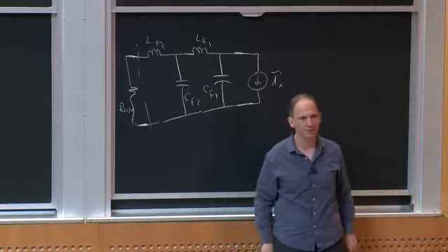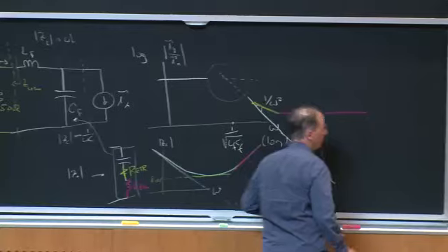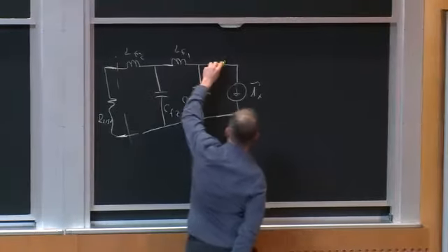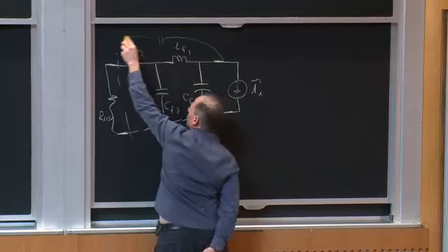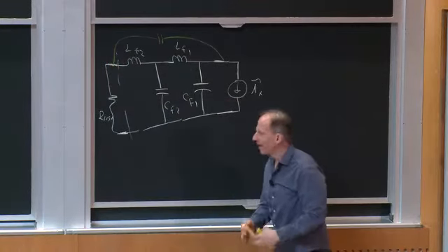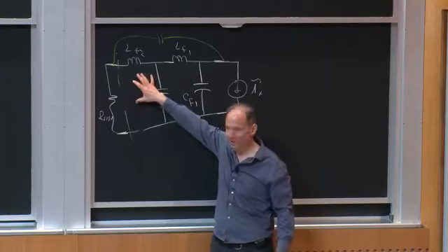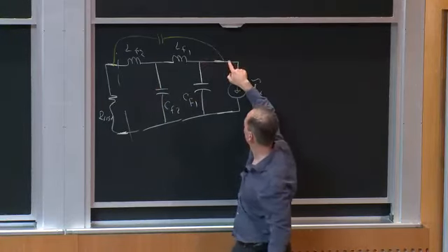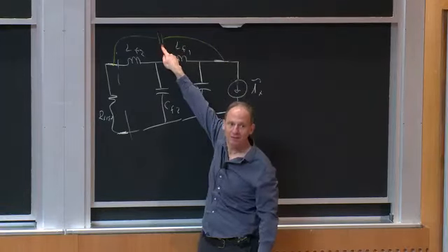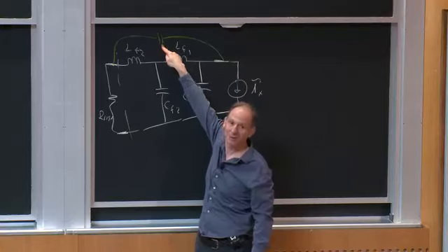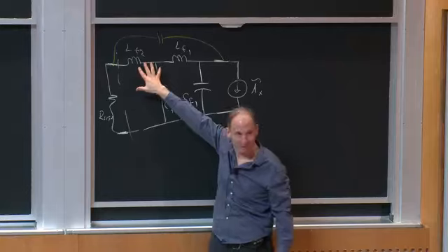What if I put those leads near each other? Well, then maybe what I would end up with is some small parasitic capacitance from this node, past my filter to this node. And so what happens? This filter is doing some great job massively killing the noise, but because this node has some switching ripple at it, it's being injected through this, maybe a picofarad of capacitance. It doesn't even have to be very much if you have a high attenuation filter. Getting over to here and completely bypassing your filter, right?